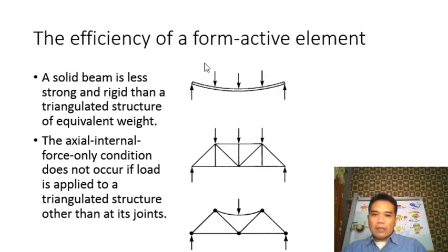Otherwise, it will be less efficient, like a single beam happening in the truss. So this is not suggested, since it creates the bending of the element. We have to remember that the purpose of the element of the truss is not applying the bending or center load other than the joint.